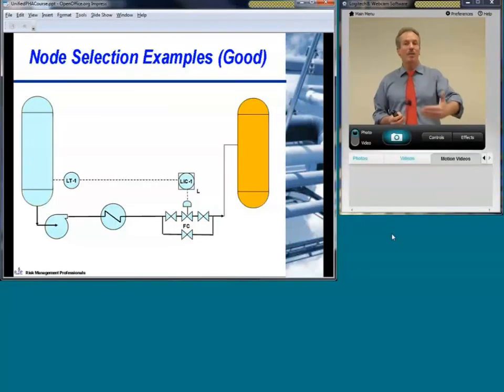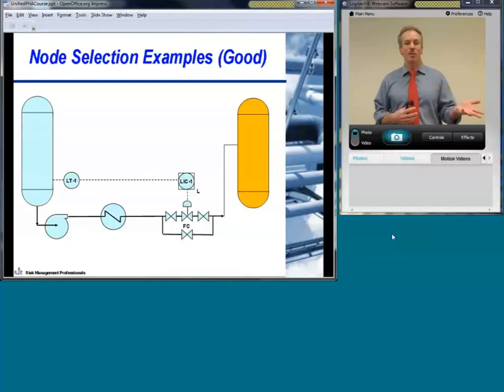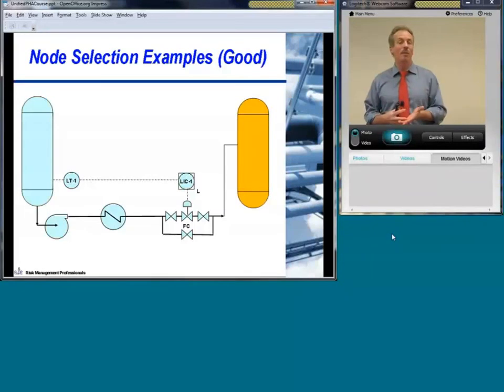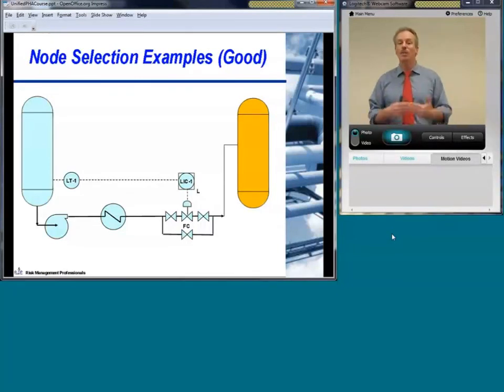If you're talking about level fluctuations in the tank, things like the pump failure, things like valve failures, are associated with that. If you're looking at pressure issues with the upfront process vessel and equipment, closing off a valve downstream of a pump can lead to a pressure issue. Temperature issues, if you're talking about a heat exchanger, whether a cooler or exchanging with another process fluid as an economizer, are looked at with the temperature deviation. So coupling them together like this allows you to go through the HAZOP study deviations very effectively, and grouping them like this really helps out a lot.